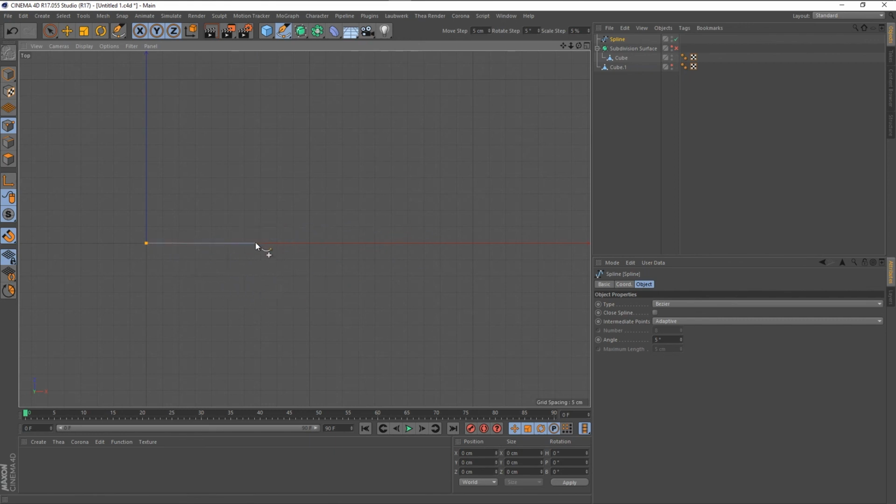So it's not like in Cinema 4D and in Photoshop, you just hold Shift key and it'll lock it onto that axis you're closest to, which would be very nice, and I wish C4D would do that. It doesn't. So you hit Shift Q, you enable quantizing, and you set your rotate and scale and steps, and now you can draw very accurate with the pen tool.